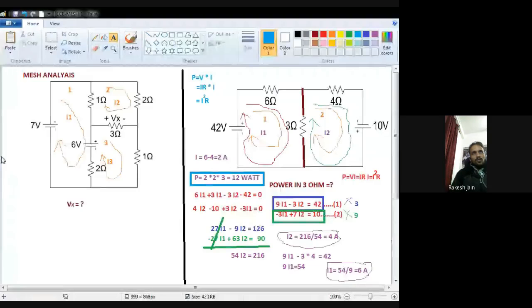So first we begin our journey with the first mesh. With this red color, I draw this one. Here I start, nothing, then a 1 ohm resistance. I write the equation for the first mesh, so my current will be I1 with a positive sign. Now through this 1 ohm resistance another current passes in the opposite direction. I am coming from top to bottom, but I2 passes from bottom to top, so I have to write it with a minus.